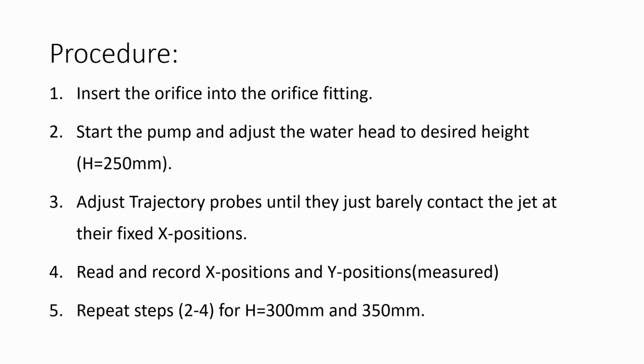Thirdly, we adjust the trajectory probes until the jets barely contact the jet at the fixed X positions. Fourthly, we read and record the X positions and the Y positions, and the Y positions that you are reading and recording are the measured ones. Finally, step 5 is to repeat steps 2 to 4 for two other heights in the water column, equivalent to 300 millimeters and 350 millimeters respectively.